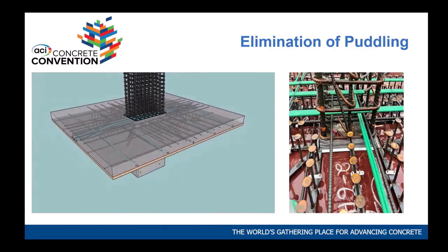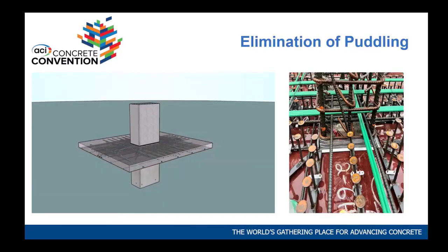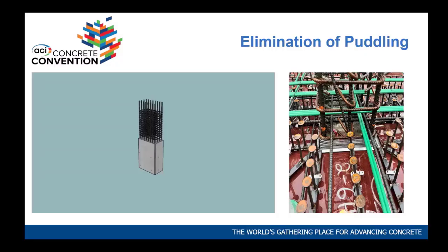Then when they pour the slab and stress it, you have this little hole because that stay form keeps the core of the column without being poured. But it does not slow construction, because you pour the slab, you stress, and you have this little cavity over the column. The next day they come and pour the column, and the concrete mix of the column goes into that cavity. It's a pretty cool, slick trick. I'm gonna replay it again, see if that works.